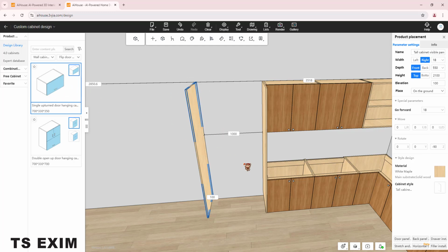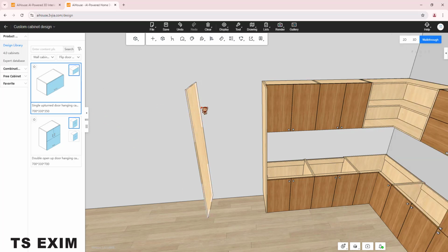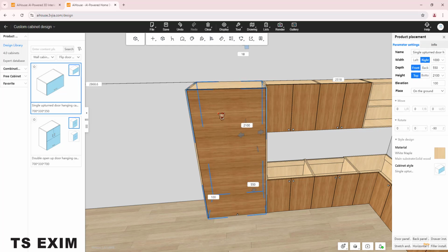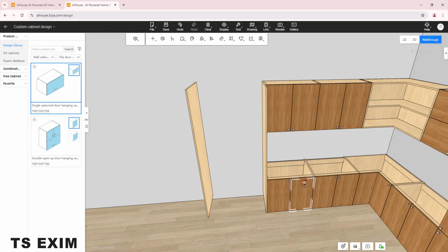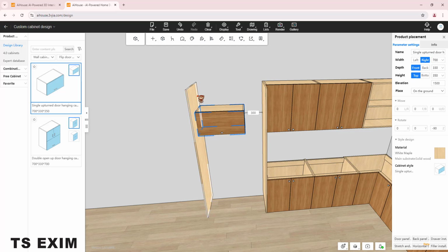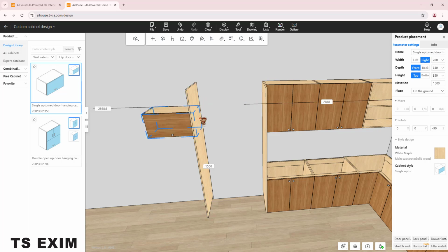So this one usually I will close the auto resize setting. I will go with no adaptation, because if you go to free adaptation and drag out this carcass, it will auto resize like this. We don't want it to resize down to the floor. So we need to adjust the sizing manually. So you go to no adaptation, make sure no auto resize, and then drag this carcass to the panel, snap it to one of these panels, and then resize it manually.